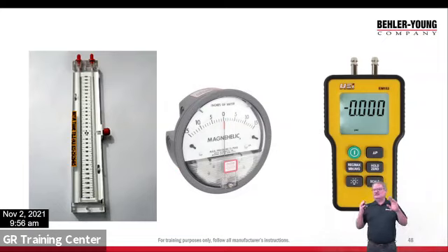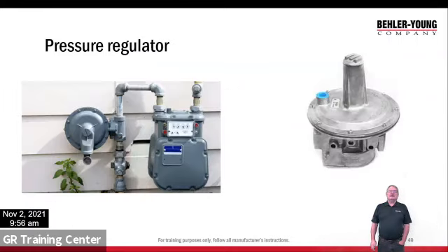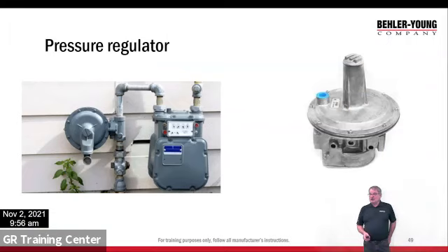You guys are getting into this at a great time because we had incline manometers and U-tube manometers and Magnehelics, and nowadays you get this one meter, which does it all. This does inches of water column, both vacuum and pressure. So I can set a gas regulator with this. I can test ductwork with this. All in one little compact meter, which is incredibly accurate. And you don't have to worry about dealing with water in the middle of winter. So now we hopefully understand a little bit about what inches of water column is and how we measure gas pressure.